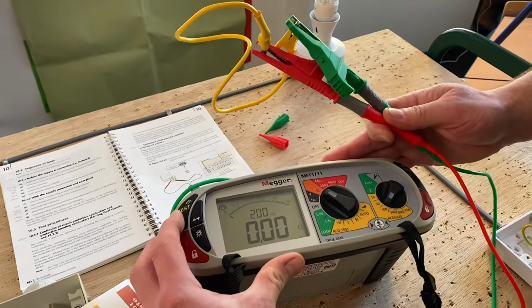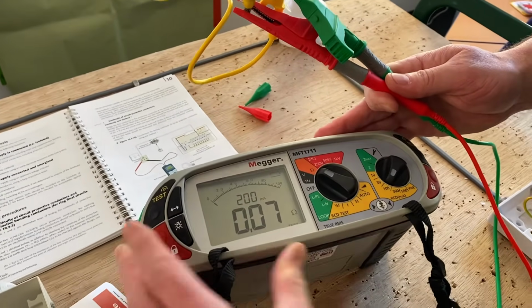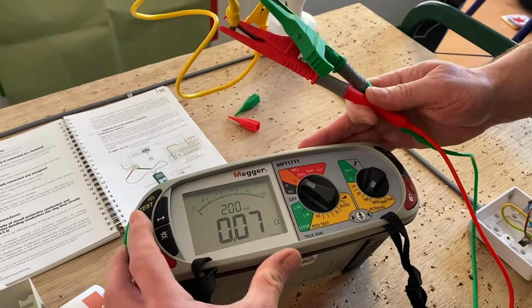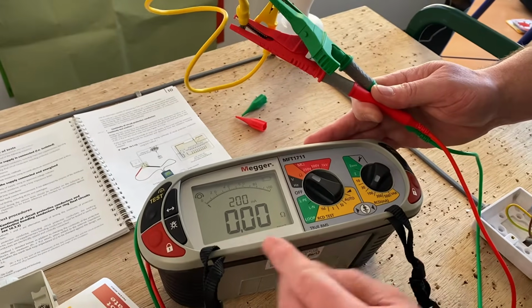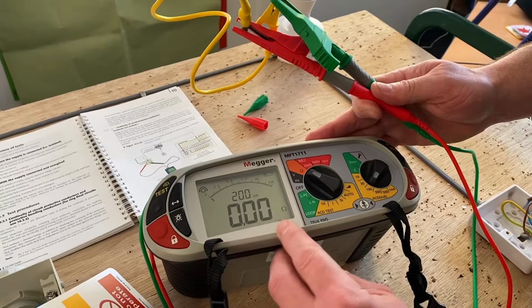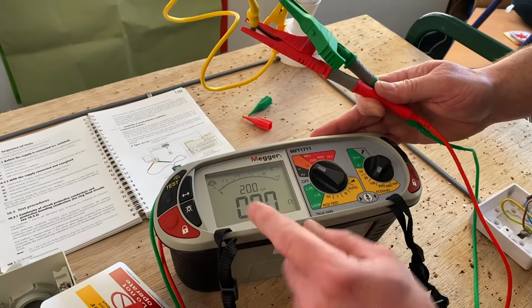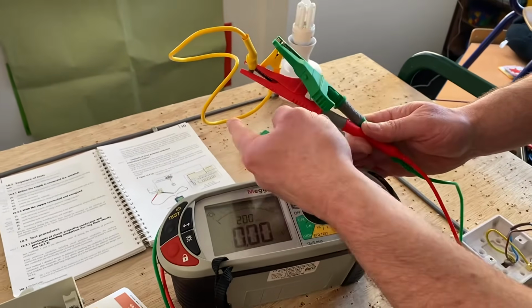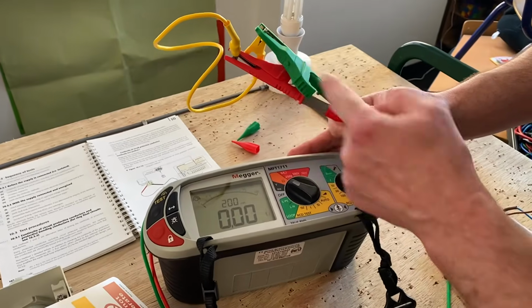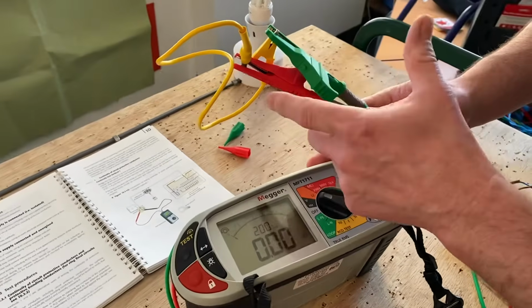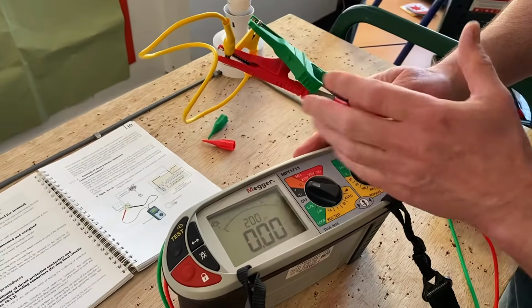We press the test button. We've pressed it once, and you can see we have a reading. I press it again, and I'm looking for a stationary 000, so that is not flashing. Therefore, I've removed the resistance of both the link and the leads, so I can perform this continuity test where I'm measuring the resistance of conductors.